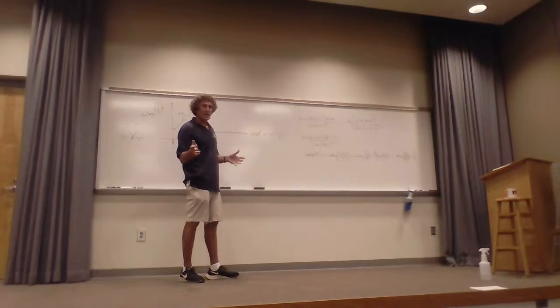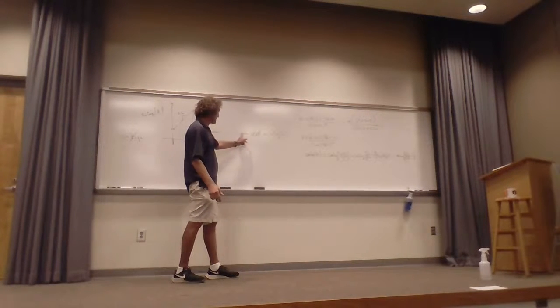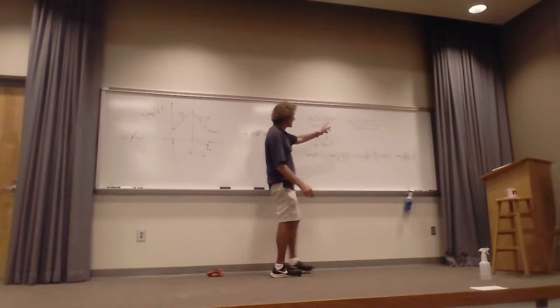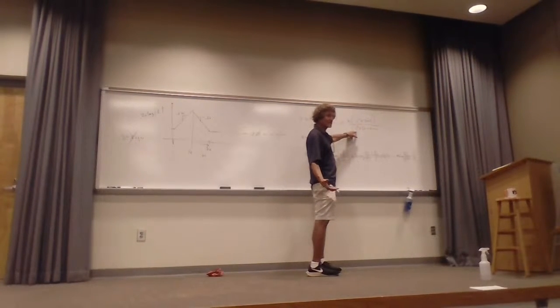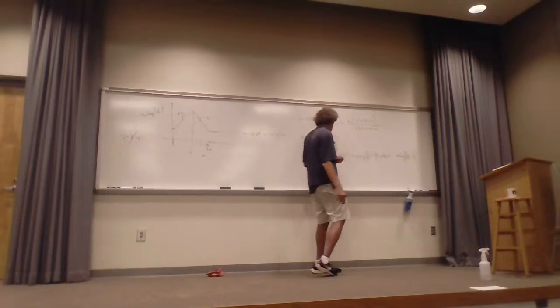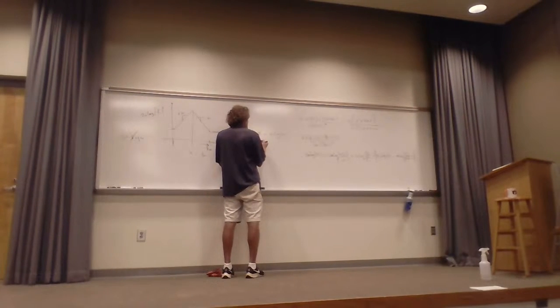If you let S get very large, and you know you're going to be out here, and therefore when you take 20 times the log of this, I've got S squared over S squared is just 1, isn't it, class? So this will happen. And if you look at this, that means I have 25 over 20, so I have 10 to the 25 over 20 is equal to K.